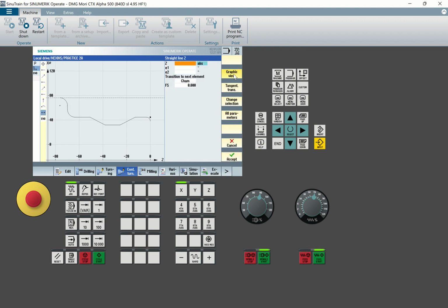Then from there I go to horizontal. Z is minus 104 plus, in case I have a tool for parting, and I can put 104, or maybe put minus 110, for example, minus 110. Okay. Then from there accept. Then go to vertical to 90 for safety. Accept. So we have a sketch here. As you can see, this is now the contour we want to cut.